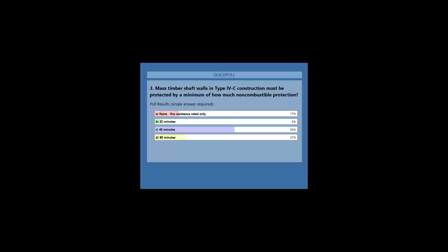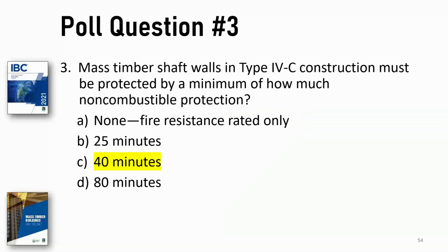All right, so I've got 70% in 45 seconds. So let's close. So 56% say 40 minutes, 22% 80, and 17% none. So Paul, what do you say the right answer is? Okay, it's 40 minutes. And let me just review quickly here. First of all, it's a shaft wall. We made a big deal that type 4C doesn't require non-combustible protection, but shaft walls do. And what is it? 40 minutes on both sides. So the key here was making sure you saw the shaft wall provision.